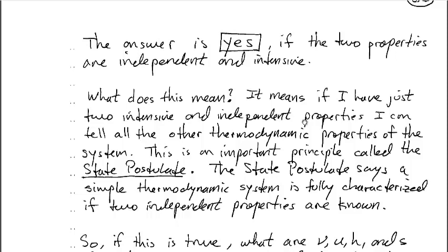There's one exception, and that is temperature and pressure during the phase change region. As we know, we cannot change temperature without changing pressure in the phase change region, in the two-phase region. And vice versa, you can't change pressure without changing temperature in the two-phase region. But outside of the two-phase region, temperature and pressure are independent properties, as are entropy, enthalpy, internal energy, and specific volume across all phases. Those four properties are always independent: specific volume, internal energy, enthalpy, and entropy.